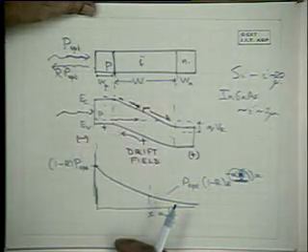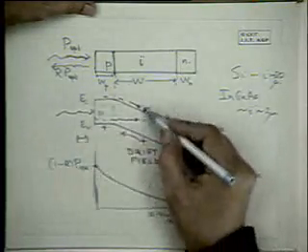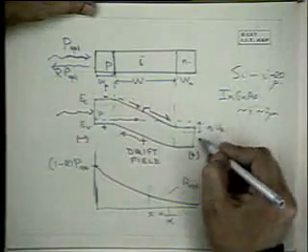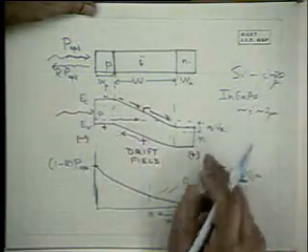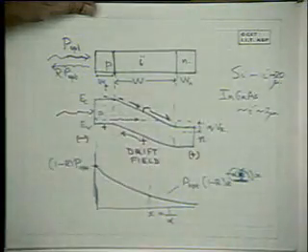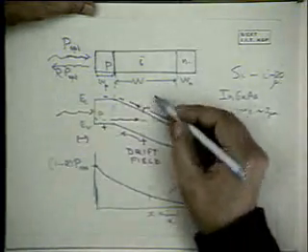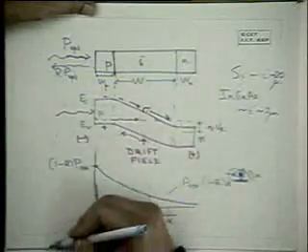Now obviously when light is incident, electron hole pairs are created, and the electrons drift to the n side. This becomes negative, this is positive. What are the contributions to this current? Firstly, of course, there are the electron hole pairs created in the I region, which are separated.